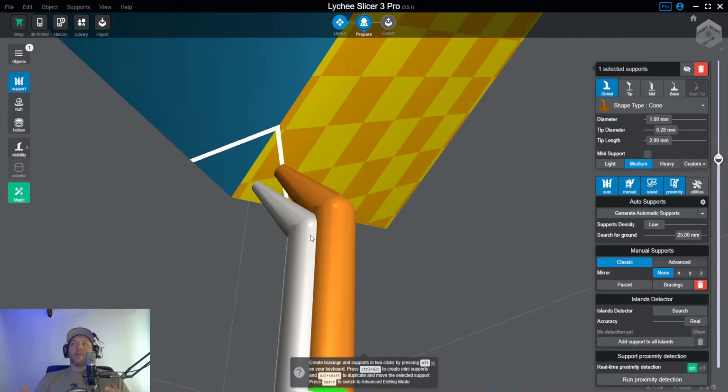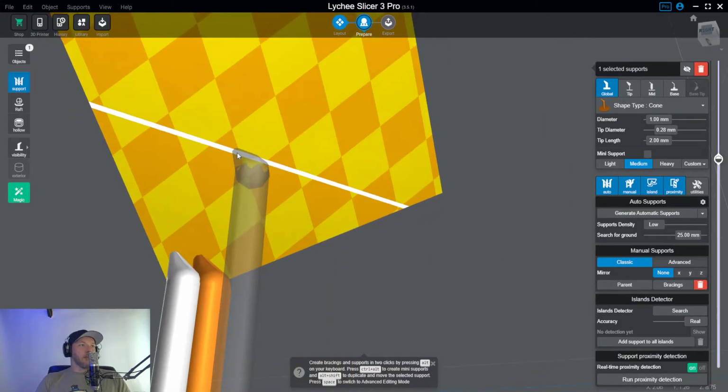So essentially, we've created 0.68 worth of surface area, but we've reduced the amount of damage to the model, right? We've created a greater resistance of force, and we've created less contact damage to our surface. Win-win, right? At the expense of using more material. So if material usage is a high priority to you, run that 0.5 if you want. But for me, I want the best quality on the model as I can accomplish. So I'm going to use that medium and that heavy. And oftentimes a heavy is accompanied by 2 mediums for me, just for extra oomph, right?